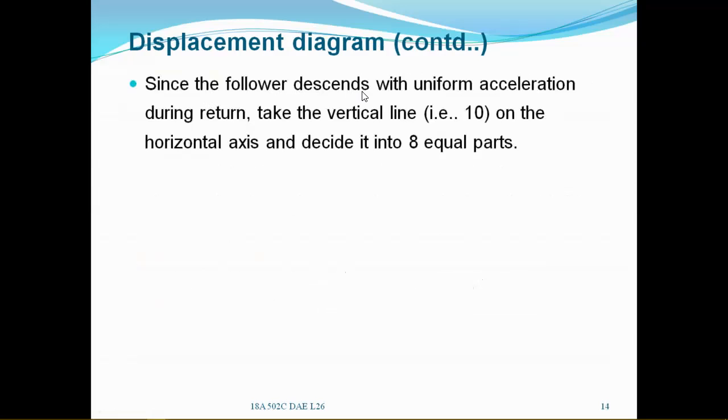Since the follower descends with uniform acceleration during the return stroke, take the middle vertical line on the horizontal axis and divide it into 8 equal parts.